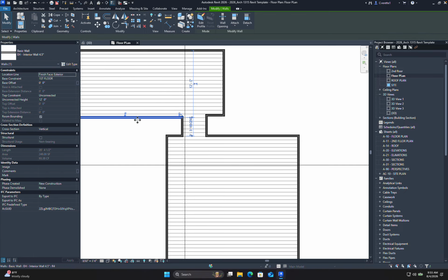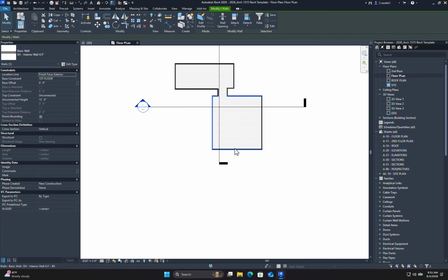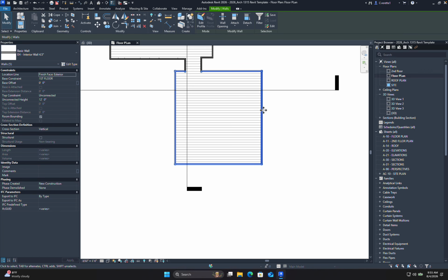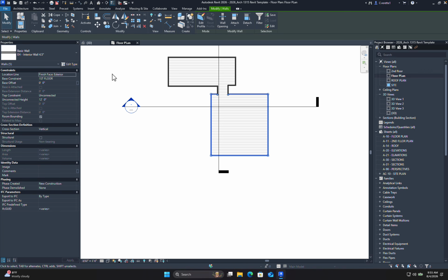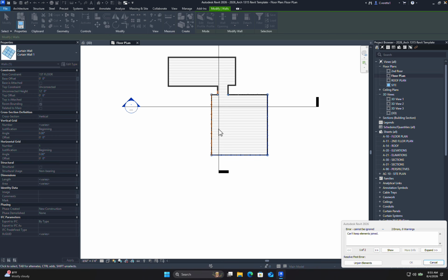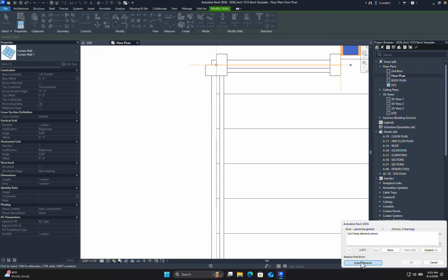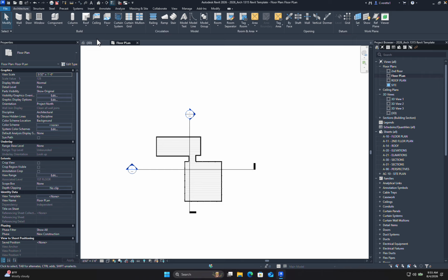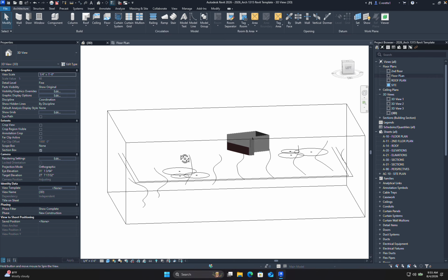But now if I want to change these walls to, say, oh man, actually I want these to be stone, I would need to select each wall, hold option if I'm on a Mac, hold control if I'm on Windows. Actually that kind of works out, both the same button. But I could basically select these walls and go, well, actually I want these to be glass walls. And it's going to say, whoa, bro, hold up. You have the wrong math here, and that's okay. You can just unjoin these elements. But I could instantly turn that into a different situation.